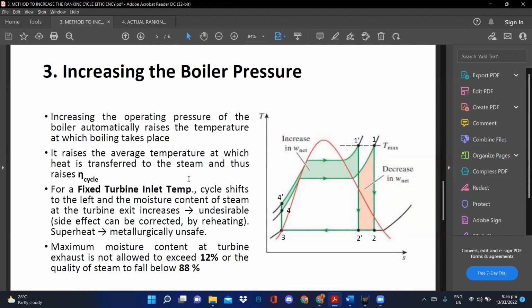And kapag siya ay patuloy pa rin na nagha-hammering, it's very dangerous, especially on your turbine or kahit hindi na sa turbine, sa mga pipeline, it's very dangerous na magkaroon siya ng water hammer. Kasi it may cause explosion or it may cause a breakage in the pipeline or in the turbine, or it may damage your turbine plate.